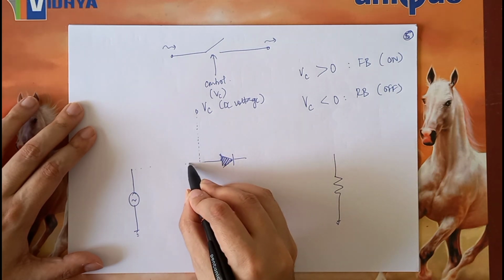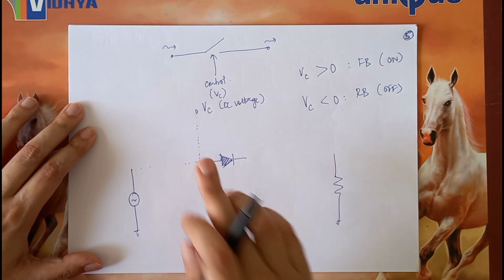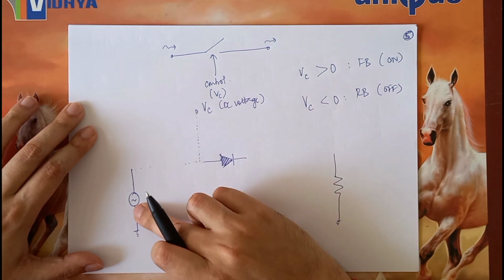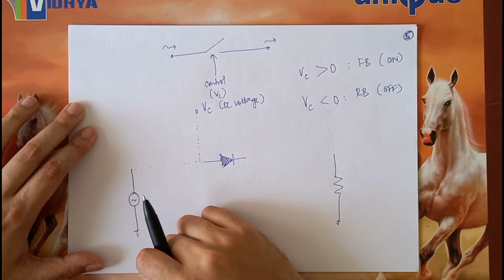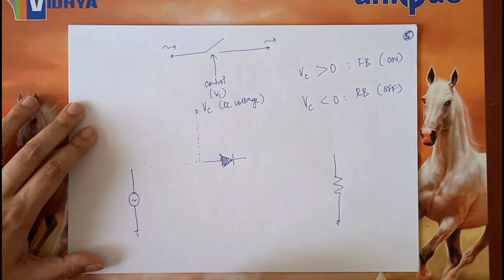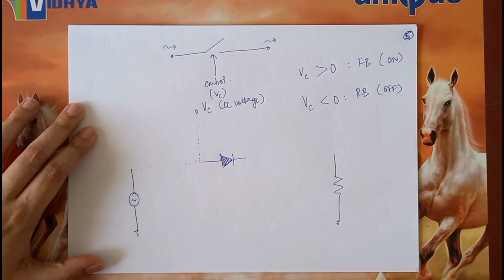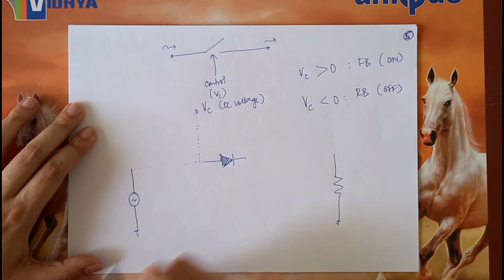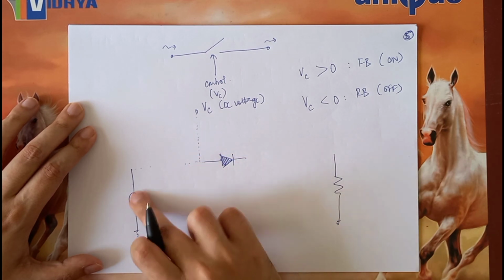Now what will essentially happen is that when this signal tries to come over here, we are breaking the circuit theorem that at the same point we are having two voltages. One is an AC voltage, one is a DC voltage, which should not happen, and therefore it will create an anomaly. You are trying to have two potentials at the same point, which is not possible. So therefore, we can take a leaf out of our biasing circuits which we have learned for our amplifiers, and let us say that we have to isolate this AC source from this DC source.